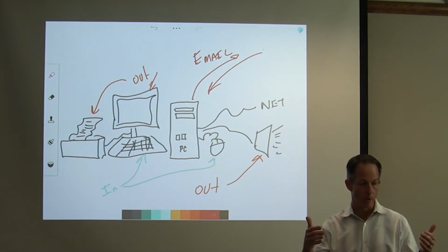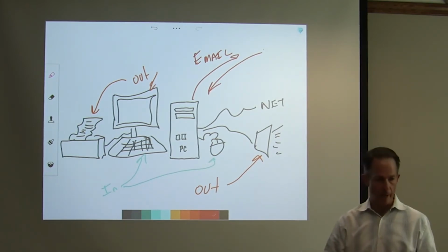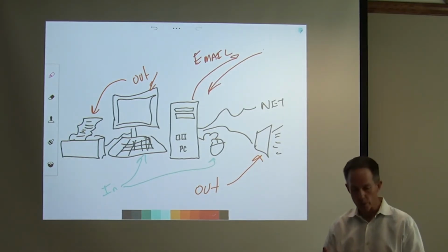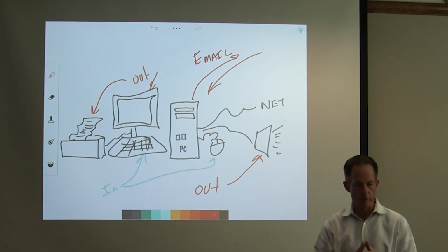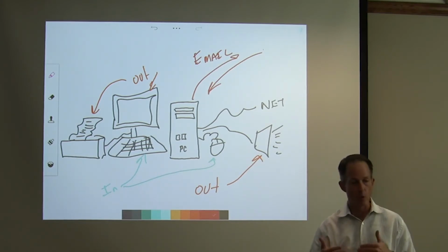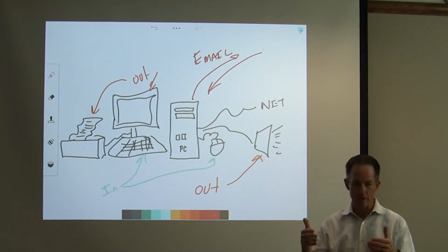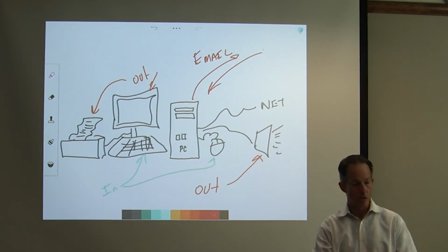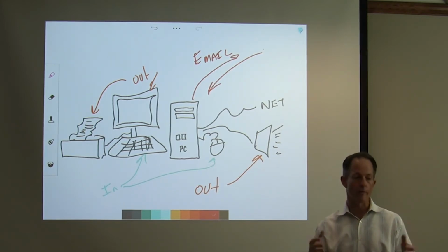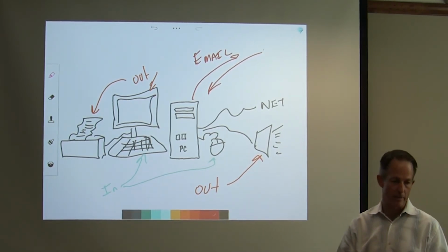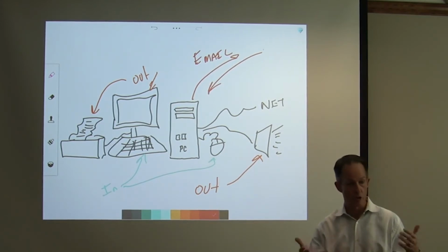We'll provide something where you can get a laptop, go right to the device. And the nice thing about Delta, and the reason that we haven't gone that way as much, is because there is a program now called IntelliWeb. IntelliWeb gives us the ability to connect right through the Ethernet to a controller and do all of the programming, add blocks, remove blocks, change sequences, set up histories, alarms. We can do all of that through the internet now, whereas before we had to be direct connected at the device.